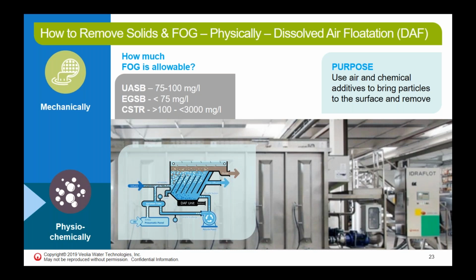Same principle as opening your soda bottle: after compressed air is introduced in the water, and then the water is released into atmospheric conditions, we form a lot of small bubbles that aid the buoyancy forces of floatable materials that have been agglomerated together using chemistry, collecting them on the top and then removing them as a skim layer as the treated water proceeds forward.